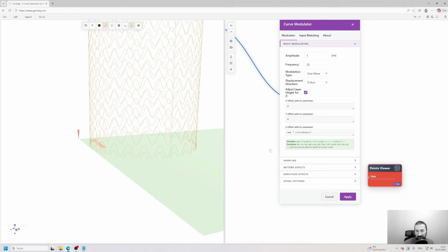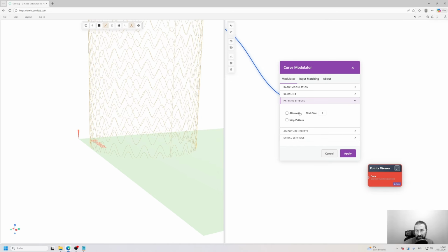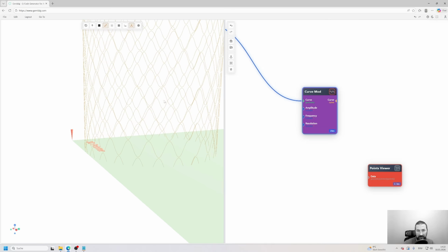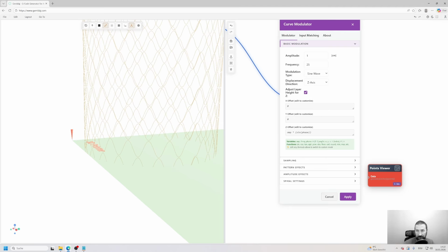You want to connect only some of them, and this is better visible if you turn on the alternate block here. You see now the tips are connecting. This will not be easy to print because you have gravity. The filament is flexible, and filament is not dry usually if you print it, so it's affected by gravity and just falls down. So in order to print in such ways, you will need to print very slow to cool down as fast as you can, and actually print at the lowest possible temperature, so it does not need that long to cool down. Also, you can decrease the amplitude. Of course, 1 centimeter is quite high. If you decrease it, print slow, and cool fast, then it will actually work.